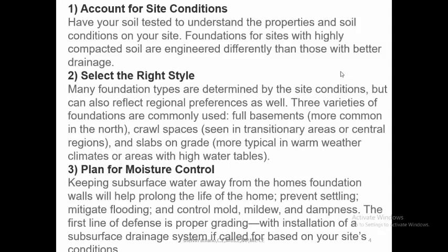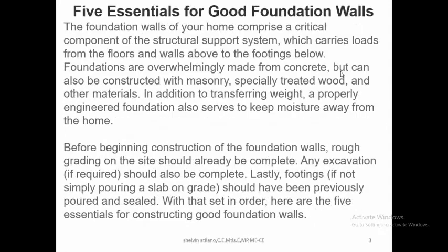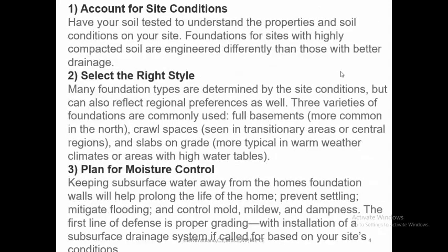Then select the right style. Many foundation types are determined by the site condition, but it can also reflect regional preferences as well. 3 varieties of foundation are commonly used: full basement, crawl space, slab on grade. Of course, it depends on the site condition. Then plan for moisture control. By the way, I'm talking about the general essentials, not only in the Philippines, but of course, it will be applicable to other countries also.